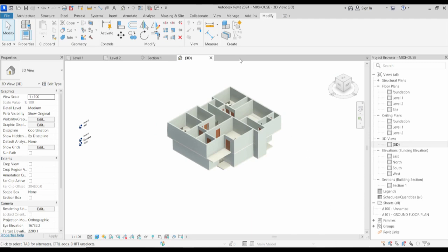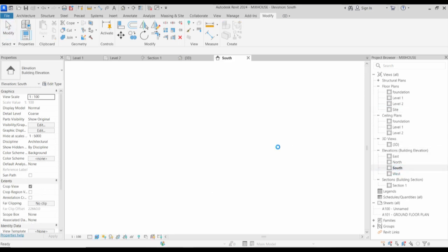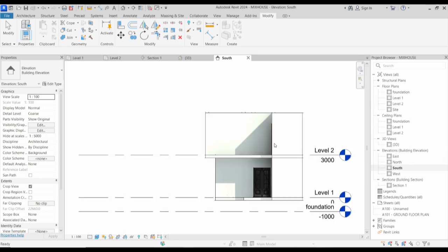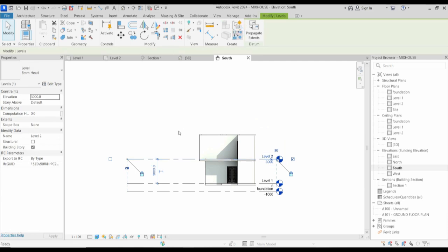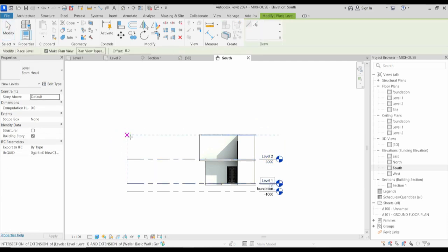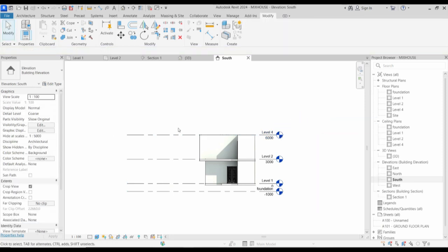So now what we do next is that we are going to start building the plan of the roof. So how do we start here? You go to plan level 2. You can decide to go to elevation and create more levels so that the roof will have its own space entirely. So in elevation, we click on this and say create similar. From here you select this and create this one, put it where this one is aligned. Then you can decide to rename it, call it roof.